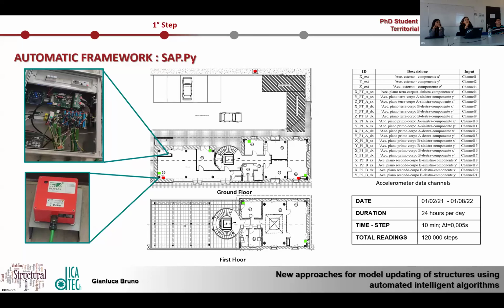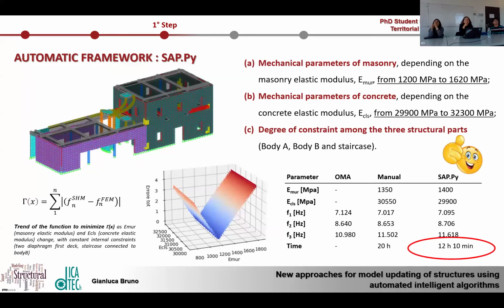Ah, okay, and how many modes were you able to extract out of this? I extracted a lot of modes, but there is a local mode. For the updating, I selected the first three modes. I saw that the frequencies were actually very close to the real ones, like the ones of your finite element model.